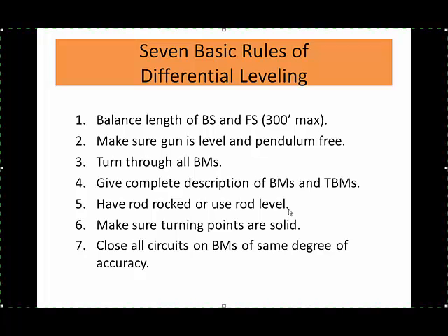Number 6, make sure that your turning points are solid. They have to be solid enough to allow 2 shots and the movement of an instrument between those shots. If it can't be stable or reproducible for that long, then it's not an adequate turning point. And then number 7, ensure that you close all your level circuits on benchmarks of the same degree of accuracy.